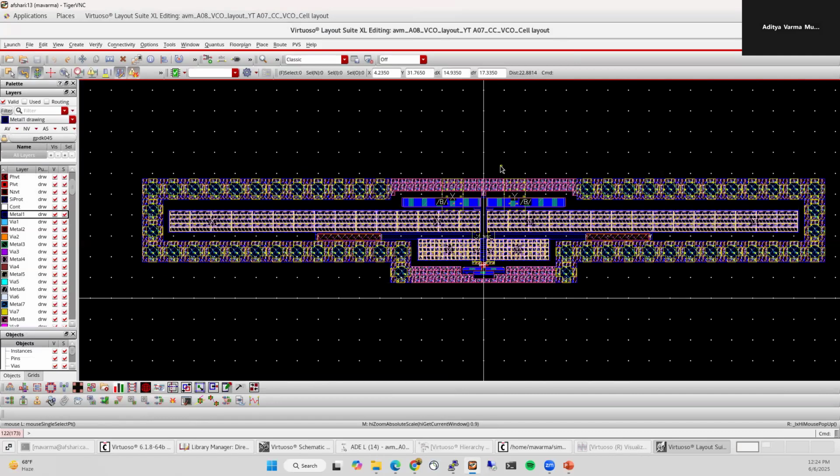Another thing we need to discuss is how you actually match, right? Right now, this doesn't have any load impedance. It's kind of open circuit. But suppose this is connected to a next stage, let's say a power amplifier or a frequency doubler. How do you match it to the next stage? Since it's an oscillator, we'll do a load pull and see how to do that correctly, and also include matching networks to the next stage. So hopefully you're excited about all that.